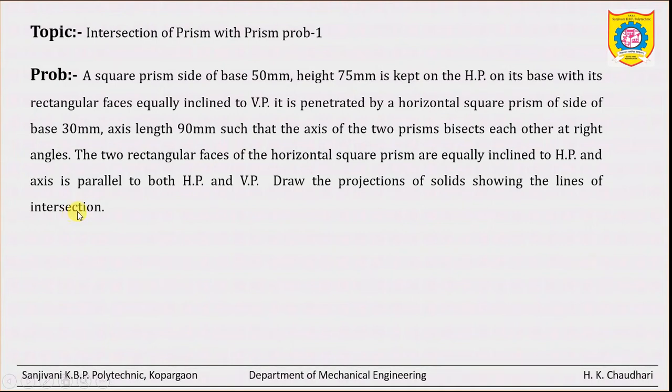So when the axes of this horizontal prism are given parallel to HP and VP, then we have to draw that axis parallel to exact XY line, correct? So let us see the solution of this problem.